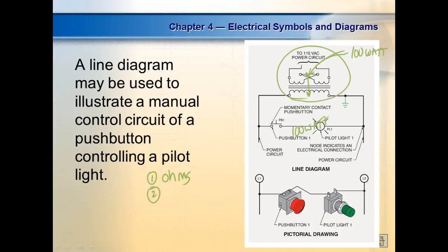Okay. So what else is it rated in? What'd you say, Charles? Wattage. Yeah. If you don't know the wattage of a resistor, then you don't need to go out and buy a resistor. We were teaching a power supply class, and they needed a 100 ohm resistor. They just looked in their kit and found a 100 ohm resistor, and they stuck it in there. And they kept coming up saying, well, Rich, something's wrong with my power supply. It keeps burning up these resistors.